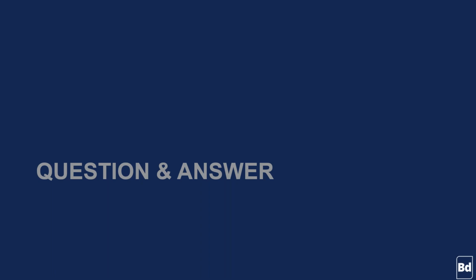Great. There's a couple of other questions. There's a question about whether our SOM complies with any specific standards. We don't. The SOM is a proprietary Boundary Devices pinout. It uses a SODIMM form factor. The reason we did that is that in the ARM space, it's not like the x86 space, where pin muxing and things like that can change between a Q7 and even various manufacturers of Q7. So it's not necessarily software compatible, and in some cases not even hardware compatible. So the concept of a modular standards-based approach is not the same as it is on x86.